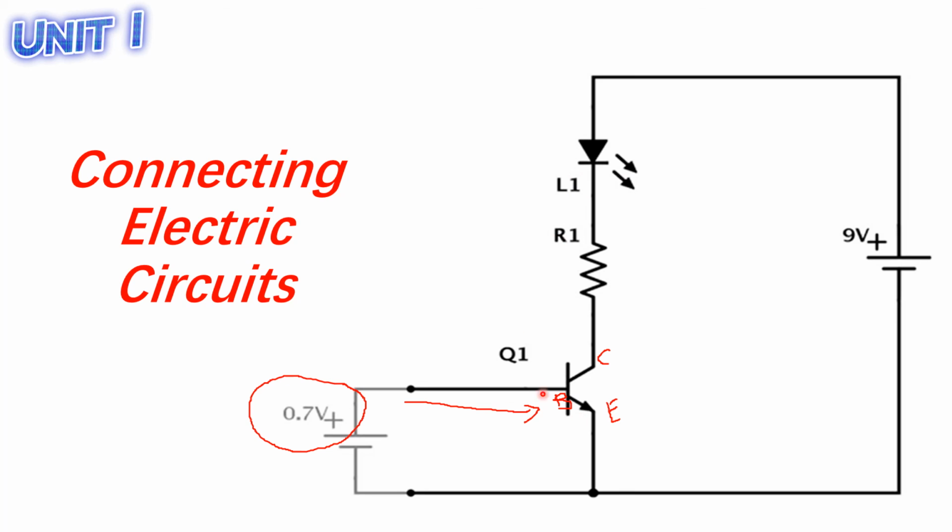Again, without the minimum voltage requirement to turn on your base, no current will flow, so meaning the LED will be off. However, if there is the 0.7 volt going to your base, it will connect your collector and your emitter. Therefore, your LED will turn on.